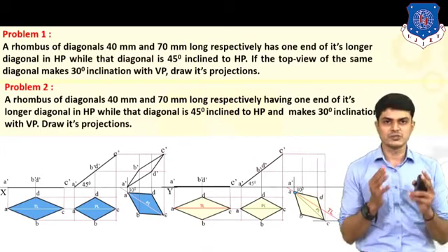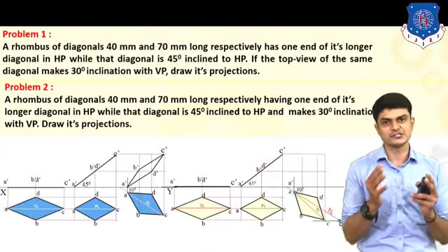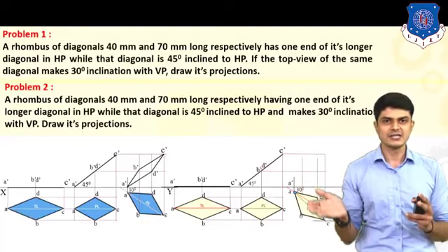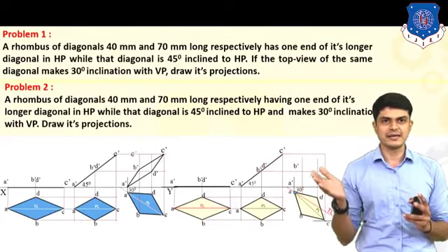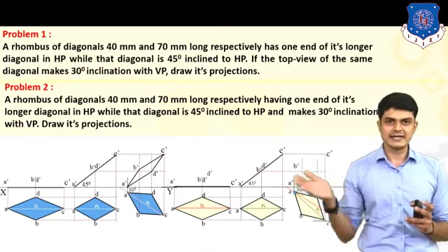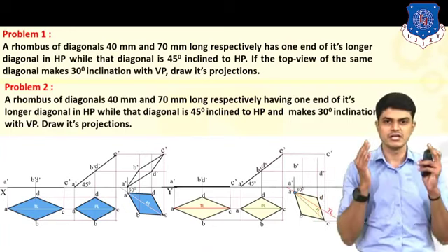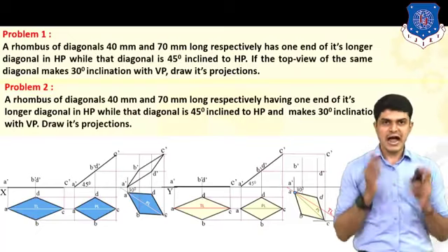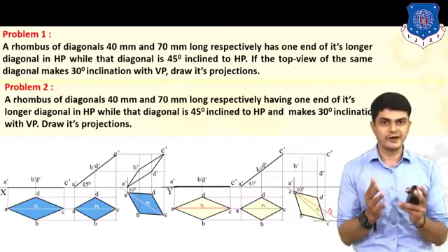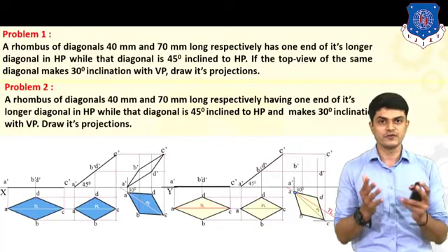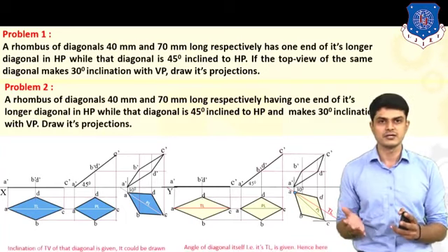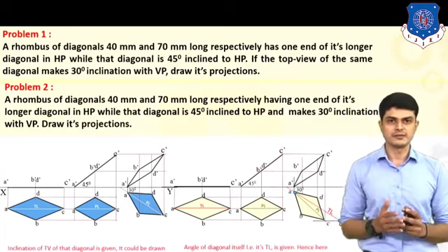Then find out the points of intersection A dash, B dash, C dash and D dash. So A vertical line and A horizontal line give A dash, B vertical line and B horizontal line give B dash, C vertical line and C horizontal line give C dash, and D vertical line and D horizontal line will give you point D dash. After having these points of intersection, simply connect these points in alphabetical order in order to finish your diagram. So let us connect these lines in alphabetical order. So this is nothing but your final object.